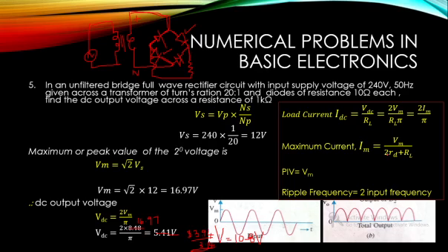That is the difference from half wave and full wave rectifier. And the peak inverse voltage is also shared among the 2 diodes, so it becomes Vm. And ripple frequency is the same as that of the center tap full wave rectifier. So here also you can see this corresponds to this position.